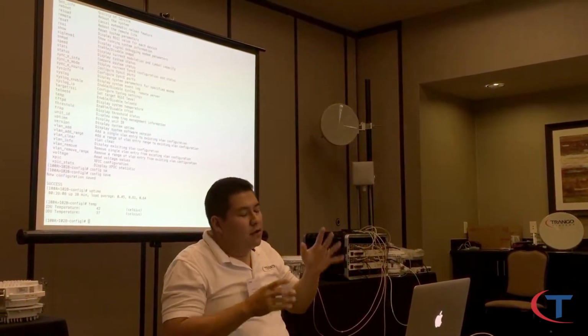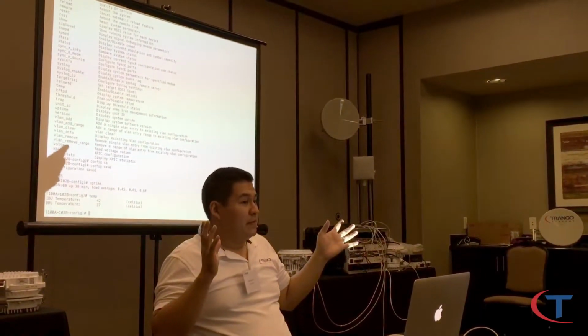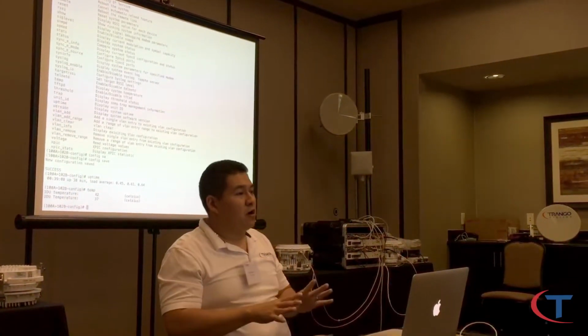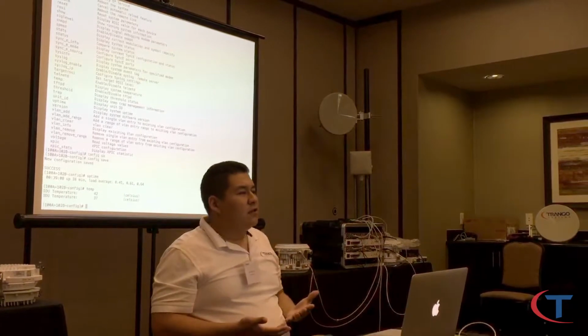The link from Black to Woodson unlocked suddenly. I scrambled to look at my ODUs. I scrambled to look at my IDUs. I didn't see a problem. I could actually get to the ODUs, turn it back on, ODU power on, and it worked. But I didn't know what the problem was.